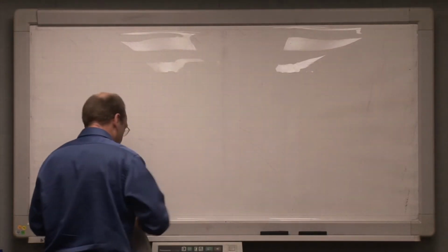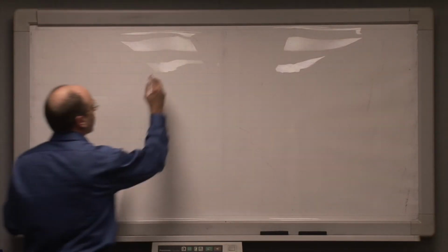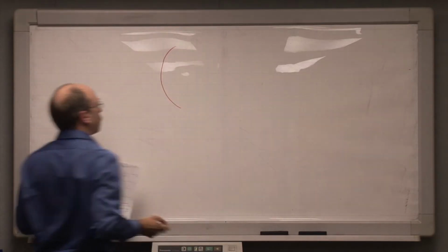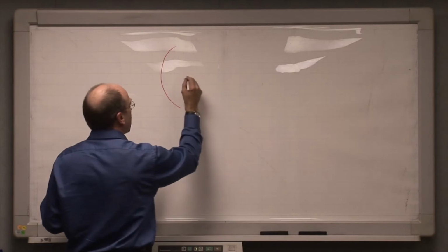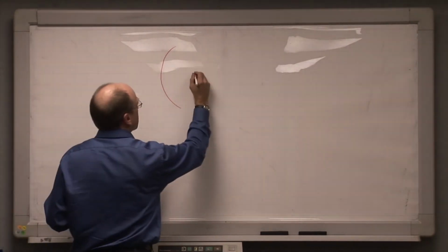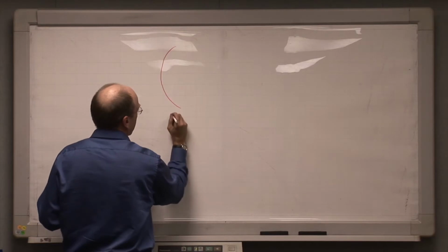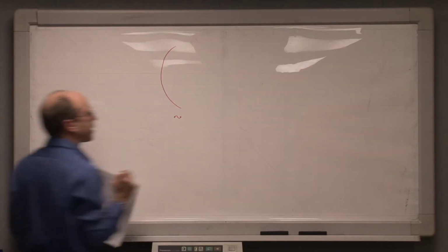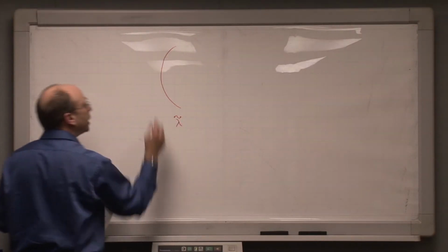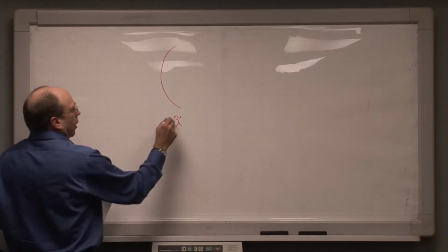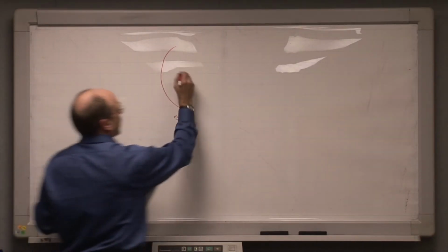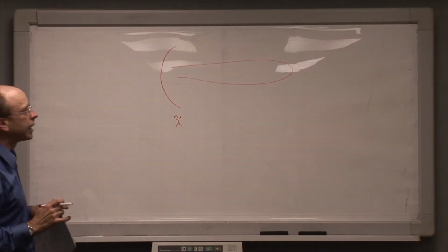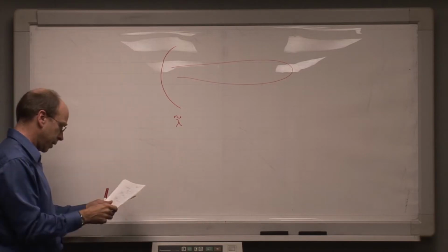When energy is interacting with objects that are substantially larger than its wavelength, then the object, whether it's a parabolic reflector or some kind of geometrically constructed device, becomes capable of strongly directing energy in space. So here we'll draw a parabolic reflector like this, and we'll draw the wavelength of the radiation that's going to interact with it like that. So here's this little tiny lambda down here interacting with this rather large reflector. When this occurs, geometrically it's possible for this reflector to produce a fairly strongly directional beam in space. It's really as simple as that.